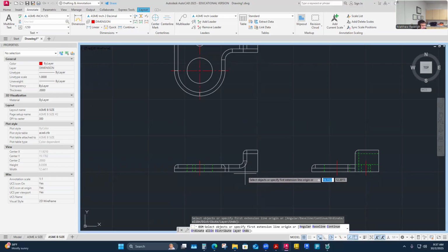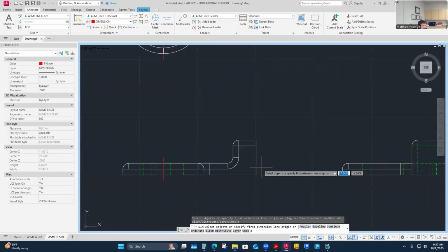So what I'm saying is for sure this bottom surface and the opposite surface of the top there, that bottom surface laying flat in the front view, that is definitely going to be a datum. It's a nice flat surface, easy to control. I can maybe control its flatness and pull dimensions from it accurately. So it's a great place to think of.